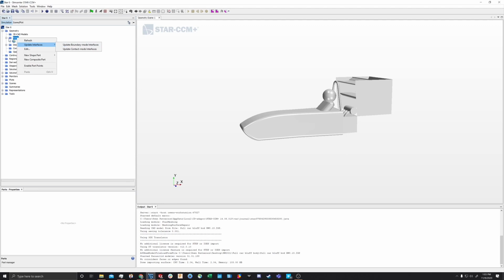There are a number of ways to go about doing this. You can make the box in CAD with the part, or with the body, the model that you want to import. It'll just come with it, and you can create your wind tunnel that way. You can create the box within the CAD engine within Star here. That's the method we tend to use for our more complex sims, where we want to really refine that box size. We want to know exactly how big it is.